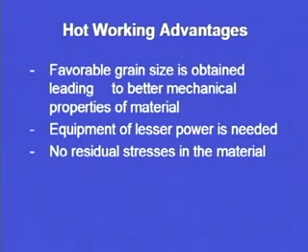No residual stresses are present in the material. When no residual stresses are present, the failures that may take place because of these residual stresses in the in-service performance of the product formed using hot working are avoided. It means the product is going to behave in its desired manner, and no failure or fracture is going to take place because of residual stresses present in the metal.